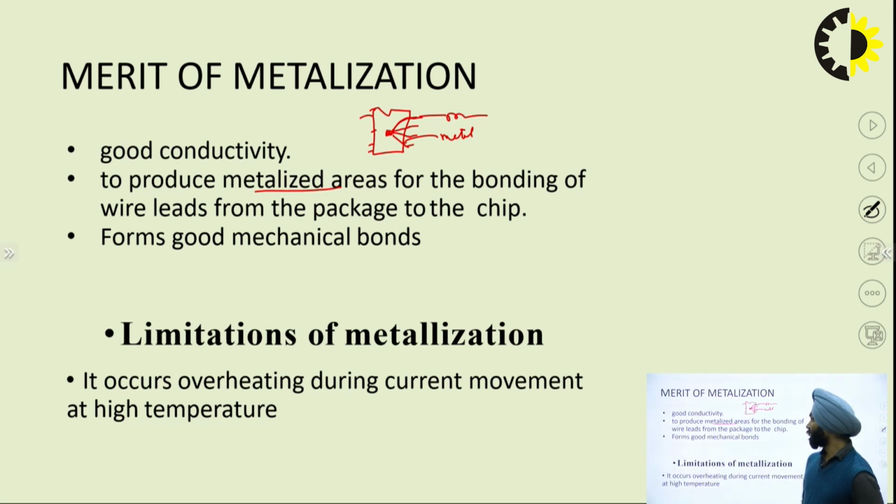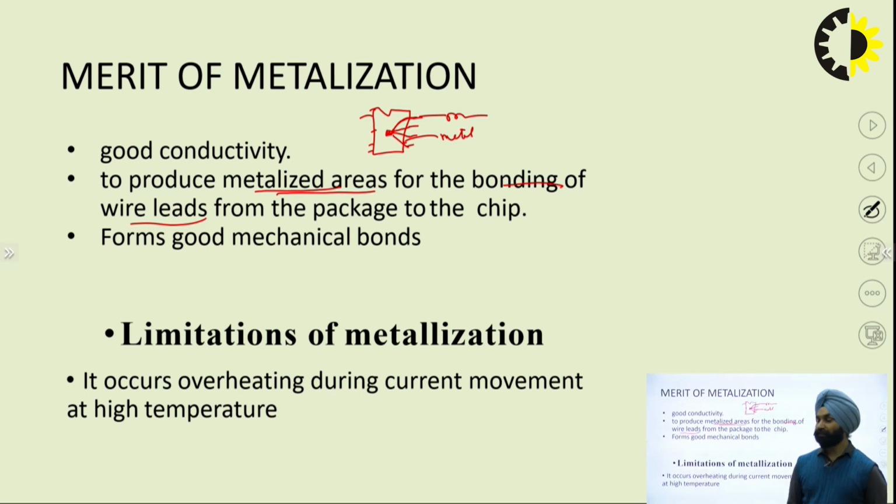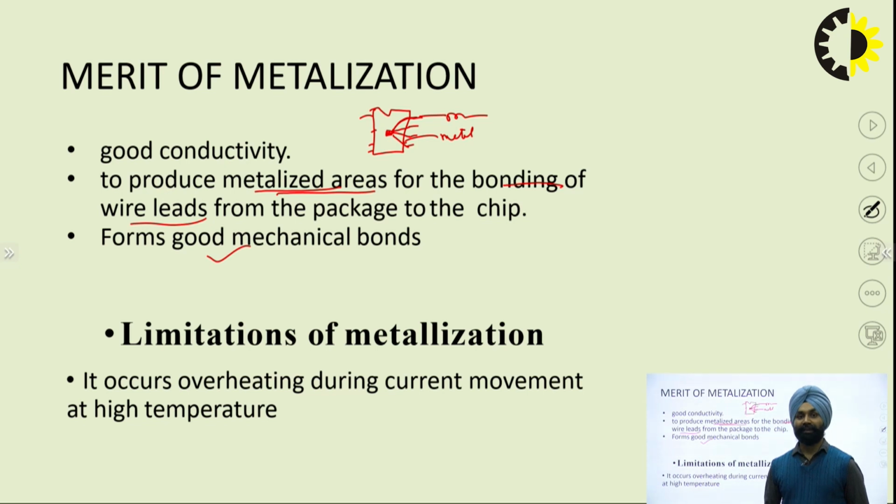So it gives metallized area for bonding of the wire leads from the package to the chip. Lastly, it forms good mechanical bonds between the circuit and the different components. Metallization gives some problems also.